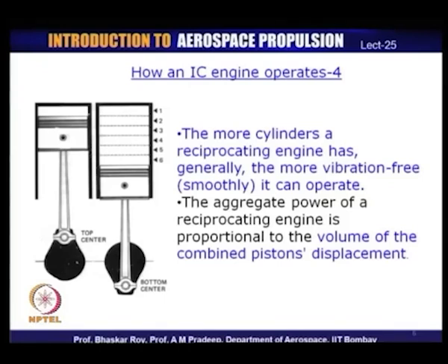If you can create an engine that is vibration free, because what happens is, as we have seen, you have 4 strokes, one of them is a power stroke, and during the other strokes the engine has to sustain itself in its motion, and as a result it is possible that there is an uneven application of force or moment on the crankshaft.